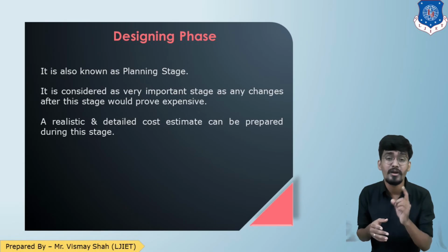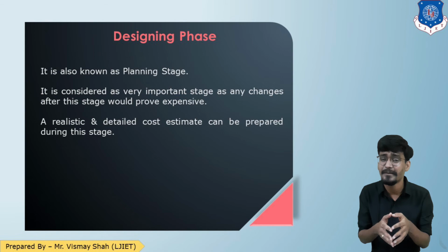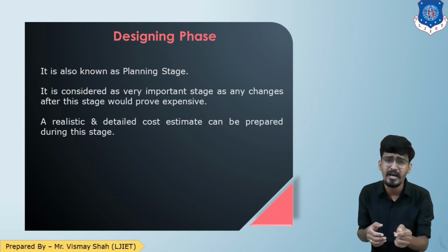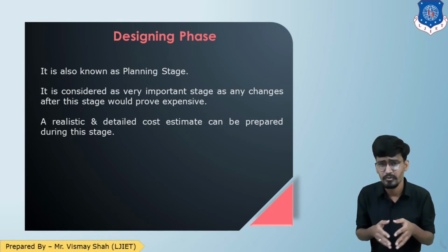It is one of the important phases, because in this stage you are going to finalize your plan, you are going to finalize how to do the work. So a small change after this stage would be very expensive to you, because you are fixing how things are done. Once the change is made, it will be very expensive. So that is a very critical stage. Here in this stage, a realistic and detailed cost estimate is prepared for the project.